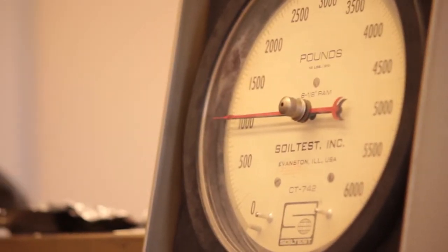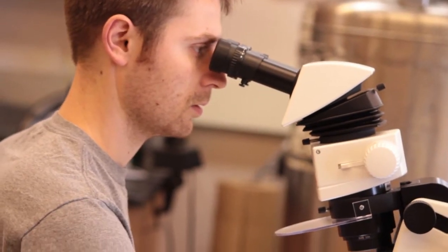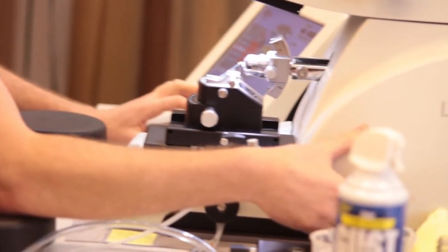At an anatomical micro scale level, wood is extremely porous and actually resembles a sponge, but you see it's absolutely full of pores. When that liquid adhesive binder that we use to hold these composites together cures, the penetration pattern, how that flows into the wood sponge, influences the bond strength.